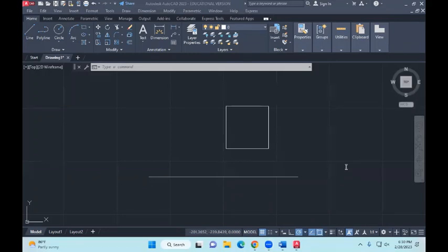Now, if you'd like to draw a circle, you can either use the dashboard, or look at the menu bar right at the top, where it says Draw. Click on Draw and then go to Circle. So execute a command and try to work with AutoCAD. Whatever instruction you give, in return it will give you feedback, so reply to that feedback. Once you enter the circle command, it will ask you for a center, isn't it? It will say specify the center. So the center has to be the top left corner.